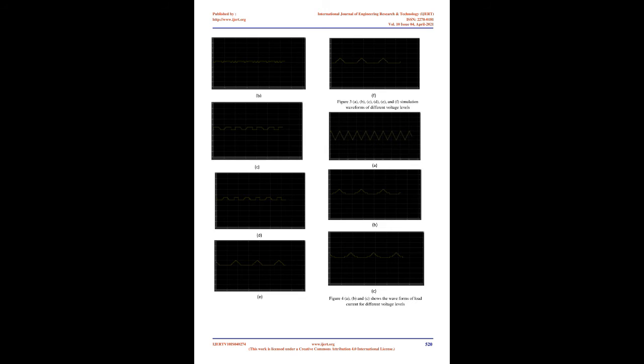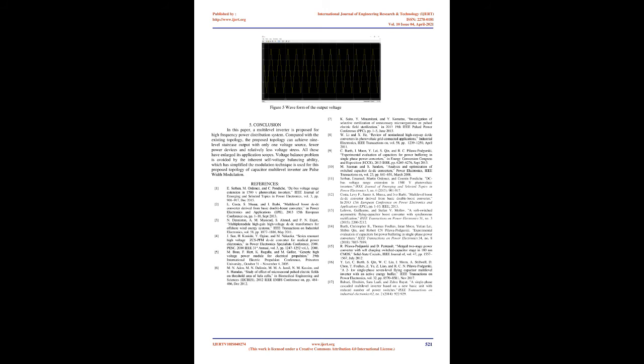Ebrahimi et al. [17] have proposed a single-phase cascaded multilevel inverter based on a new basic unit with reduced number of power switches. In this paper, a new single-phase cascaded multilevel inverter is proposed. This inverter is comprised of a series connection of the proposed basic unit and is able to only generate positive levels at the output. Therefore, an H-bridge is added to the proposed inverter. This inverter is called the developed cascaded multilevel inverter.